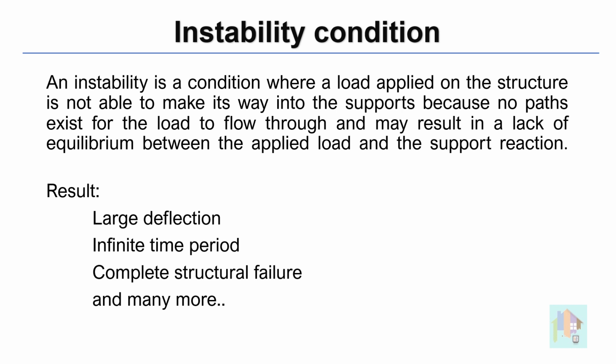There are different reasons for instability, which I will discuss in detail, but the primary reason is simple. Applied load on the structure is not able to make its way into the supports because no load path exists. Zero stiffness problem, which I discussed in the first part, is one of the reasons for instability.